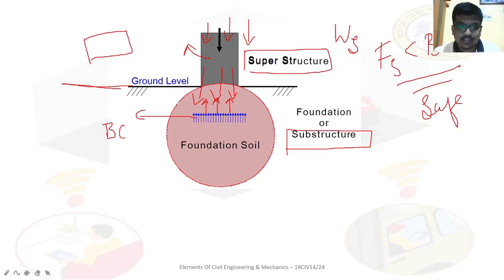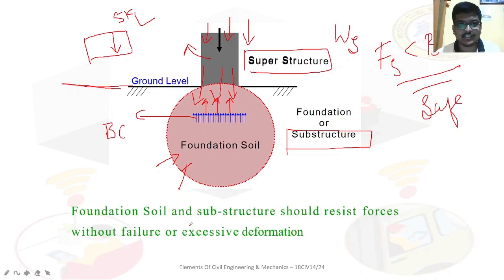Suppose you have one type of soil which has the bearing capacity to withstand only 2 floors of a building, but you design a building for 5 floors. Whenever that 5-floor building is built on this ground, it will settle down. Your money is wasted, materials are wasted, everything is wasted. Because of that, the preliminary survey, the preliminary detail to be collected before any project, is to study the soil condition of that ground. For this, geotechnical engineering is very important.